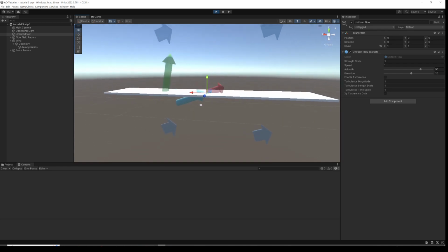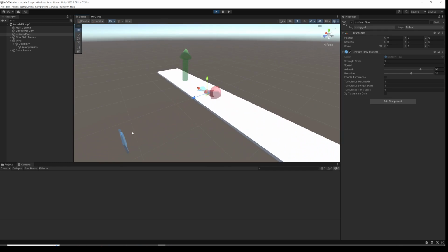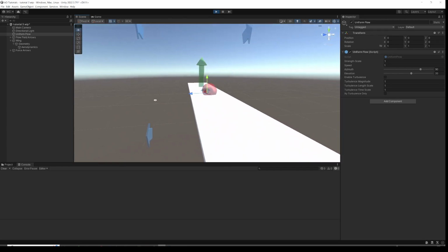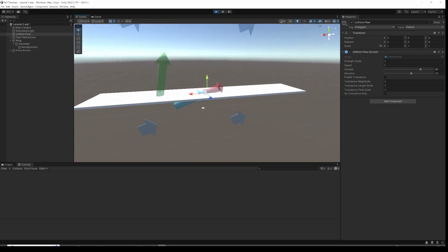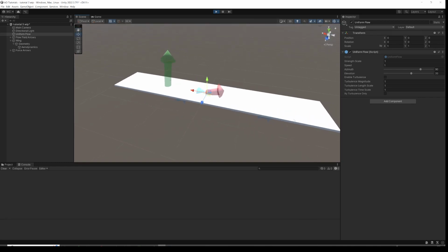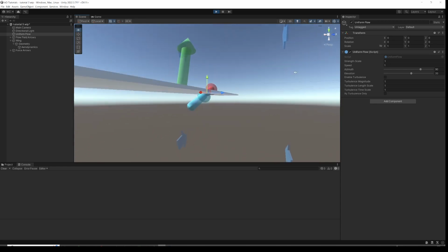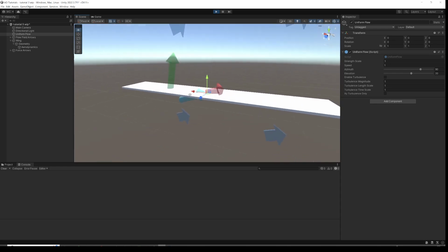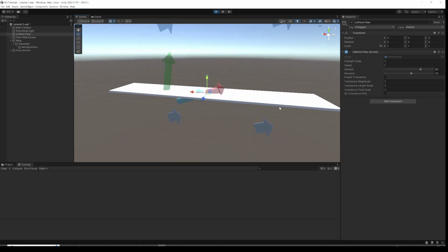Imagine this is a ruler someone's thrown in the classroom, flying at an angle like that, but it's like a really thin wing, so it hasn't really got any wingspan at all. It will still produce some lift and quite a lot of drag, and Aerodynamic Objects is happy with that, given the shape of the wing, the angle of attack, and the angle of sideslip. The lift model will calculate a reasonable approximation of what the lift would be. If that really was a ruler flying across the classroom, this would be a fairly decent estimate of the lift and drag. We can carry on all the way around, and then we're back to where we started, just going backwards.